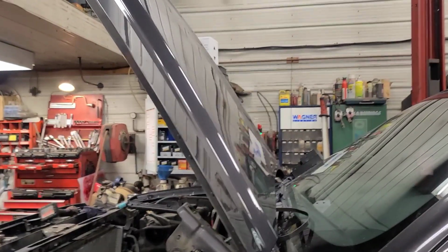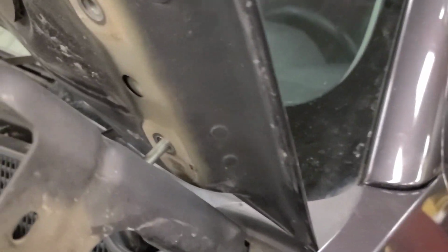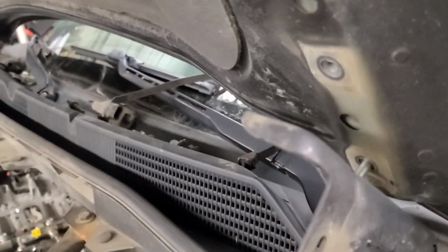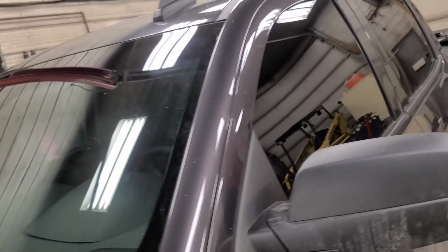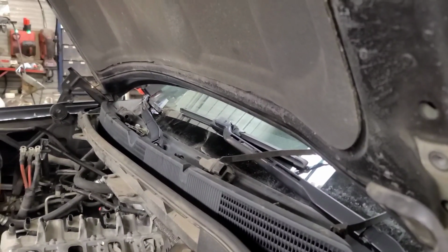In case you're wondering how I got the hood open far enough, take the 4 bolts out, put 2 longer bolts in the bottom, and then tip the hood back. I put body washers so it can't fall out. It sits on these rubber mounts on the corner here, and I use a big ratchet strap to tie it to the back bumper. Hold the hood open far enough. I'm going to leave it like that till we're done.